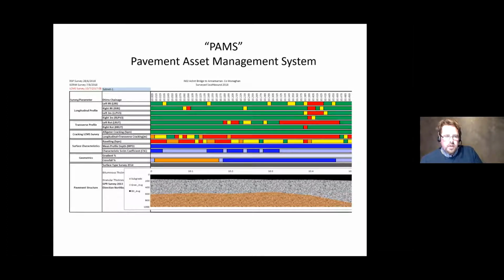The one thing to watch as well is that the crack testing, which is carried out with the laser crack measurement system, was carried out last year, but it wasn't carried out for a period between 2017 and 2019. So if you're looking at data from 2019, you might not have current LCMS data. So cracks you see on site might not show up on the LCMS. You might also want to be conscious that joints might not show up on the LCMS, especially your central line joint. Joints will show up as cracking.